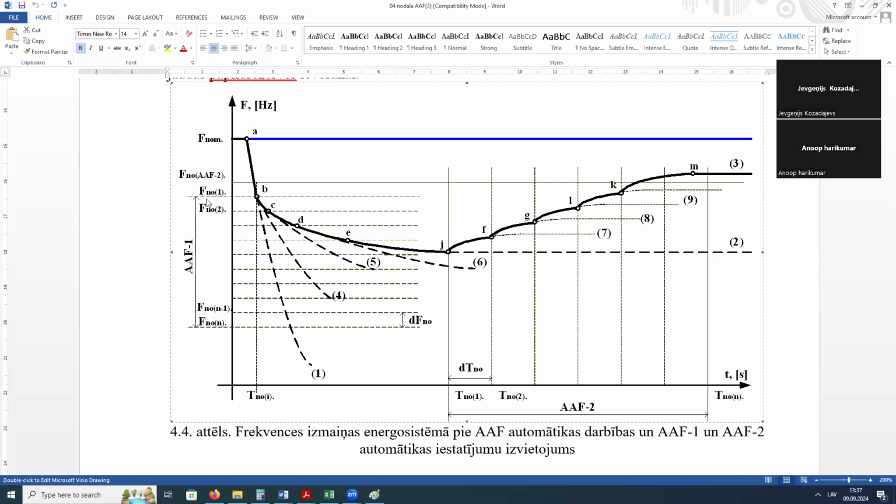First of all, the system automation doesn't know what the shortage of energy is, because, as I mentioned, the difference in frequency is not so easy to convert to power. We need a model to do this, a very detailed, complicated model.